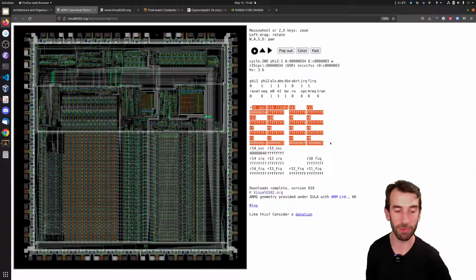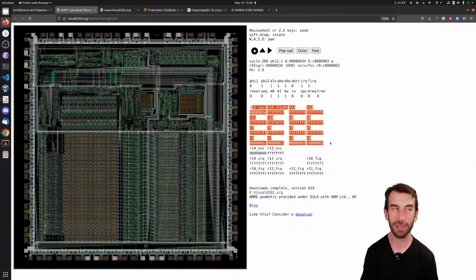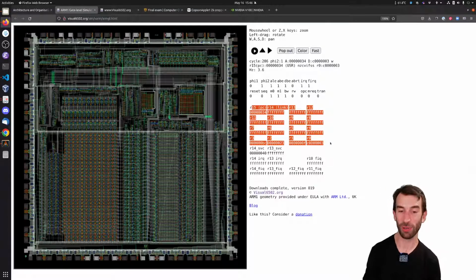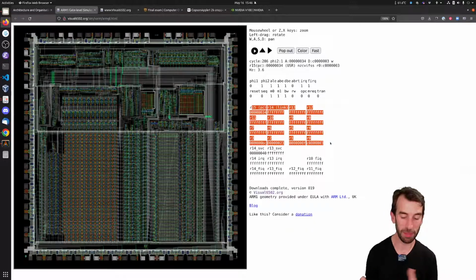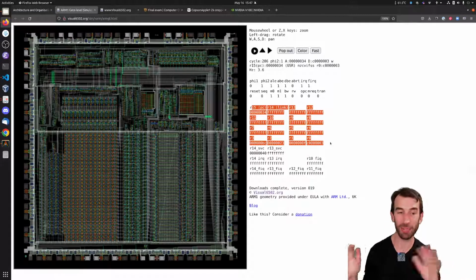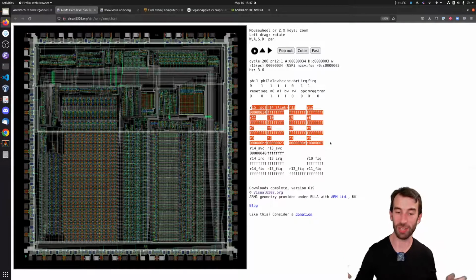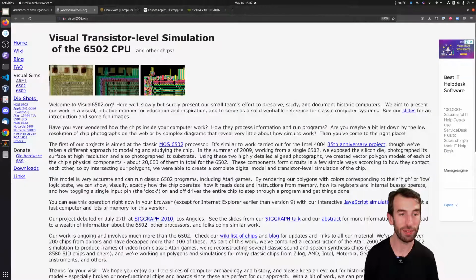And that's one of the features of RISC computing, that you have more registers because you need to store more stuff temporarily while you're doing things with your instructions. You're doing multiple instructions to get the same result. In CISC computing, it was more like you get something from memory, add it to something in a register at the same time, and then put it somewhere else in memory immediately. Things would all happen in one complicated instruction, which can speed things up, but it makes the architecture a bit more complicated.